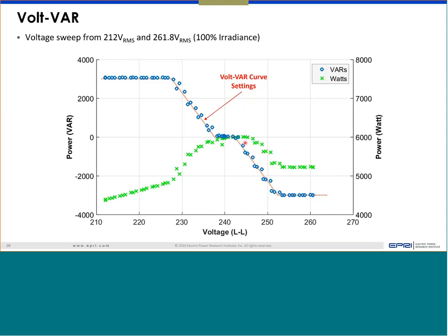And you can see the corresponding power value if you go vertically. So immediately after a couple of voltage points, the real power did not change because maybe this inverter has some reactive VA limit available, so it can provide reactive power of a certain magnitude without reducing real power, if you remember that Pmax and Smax question. But at a certain point, when reactive power becomes large, it has to reduce the real power to produce the reactive power. It's a 6 kilowatt nameplate. So at this watt, it has to reduce the power to provide room for reactive power.